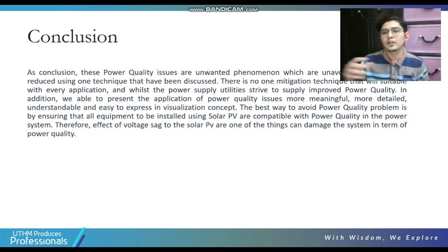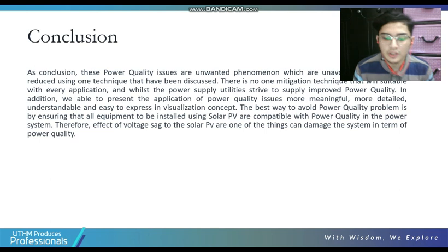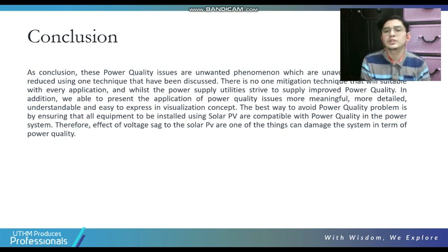So from there, we used a circuit of DVR to make sure the signal of voltage sag can be reduced, between 0.03 until 0.08. The controller shows good performance in addressing and enhancing the output voltage. From the simulation, it is clear that it shows the improvement of these two factors and how they affect the performance of the DVR. Therefore, when it comes to implementation, it is crucial to consider these factors so that the performance of the DVR can be fully optimized. So I think that's all from us. Thank you.